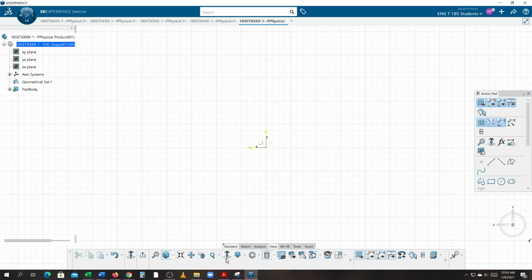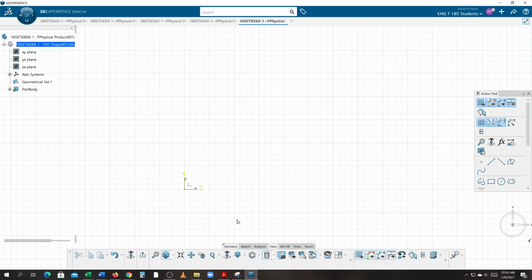But horizontal is now going to the left. In all graphics we've learned in all math classes prior to this, horizontal goes to the right. So right is positive and left is negative. If you hit Normal to View one more time, it will flip it so that you're looking at the axis where H is horizontal and V is vertical. I can slide this over here and go to the Sketch tab on the bottom to create my rectangle.